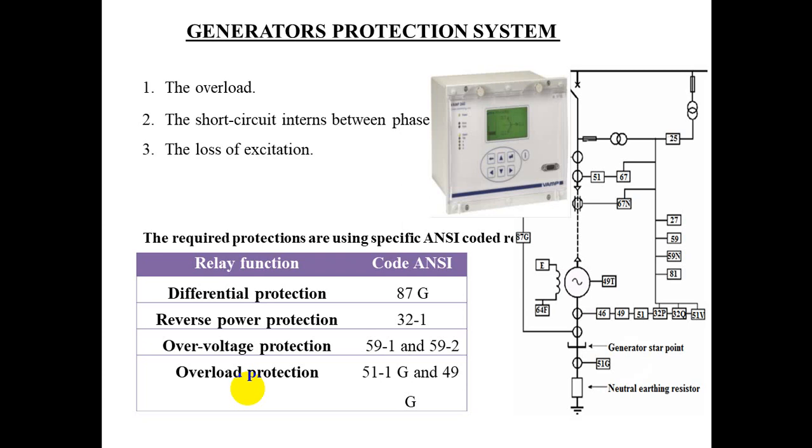To minimize the distortion, it is common practice to turn the rotor at low speed during the cooling down period. In view of the forces involved with the large modern rotor, it is now standard practice to fit shaft eccentricity detectors.